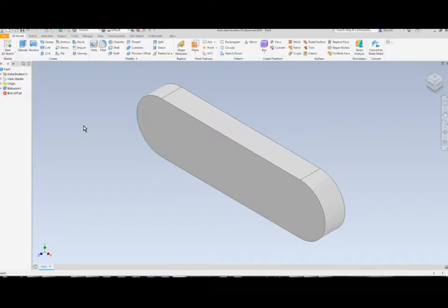The refinement process is going to be: I am going to create two individual bosses on both ends. They will be identical to the diameter of the outside edges. And then on the inside, I'm going to extrude cut to remove half of what the total width is. So with that said, I'm just going to go and click on my start sketch.